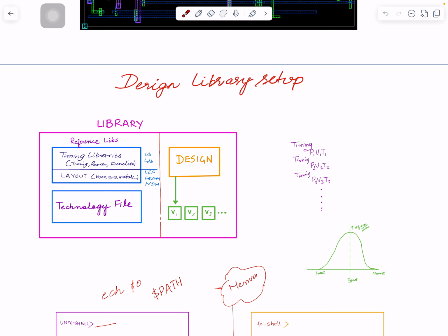There's a function attribute on every cell, so open the library. There is a .lib file, which is a text file. You can open it in less or vi. I typically use the less editor in Unix for read only. If I have to edit something, then I use vi. So I use less on that lab. This is a binary conversion of this one, LDB or DB. Some people use LDB, some people use DB directly. This is a binary format. You cannot open this one, but the .lib will open. So open that one and look at what is inside.